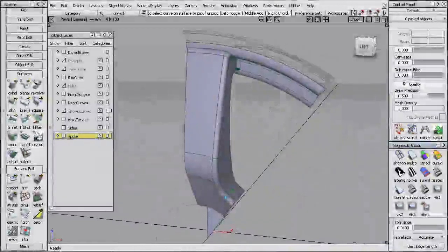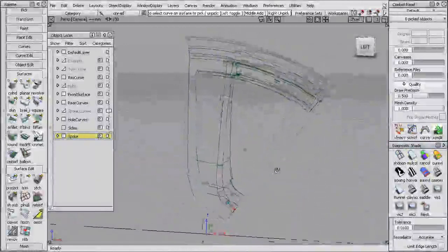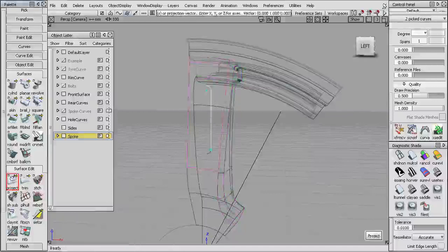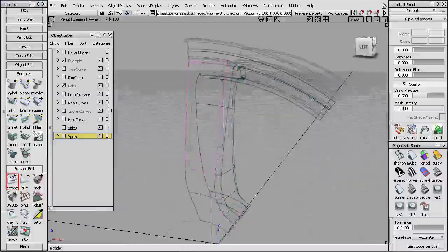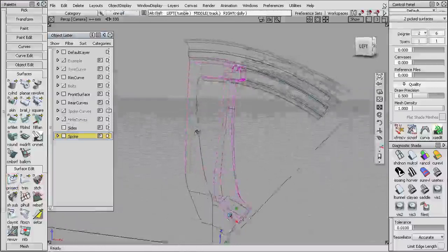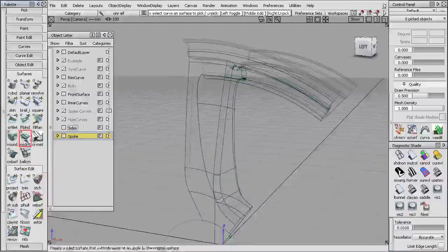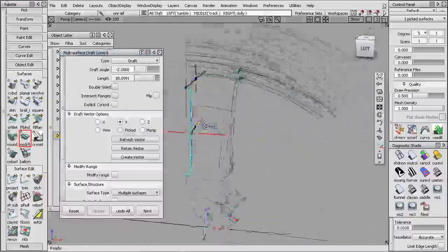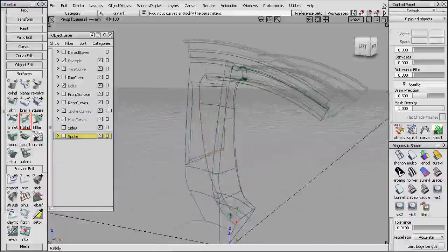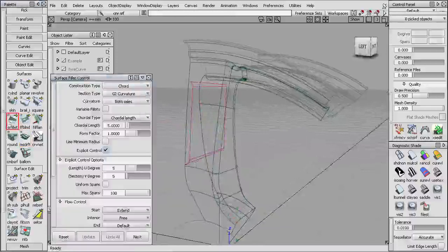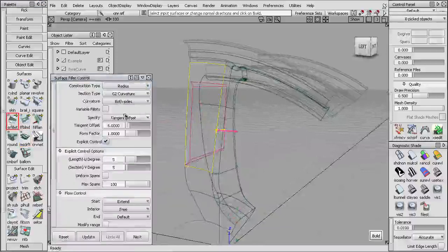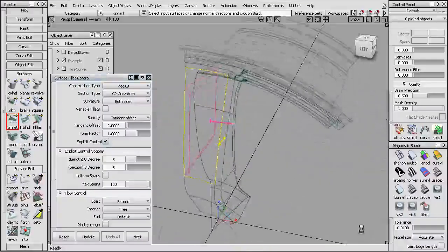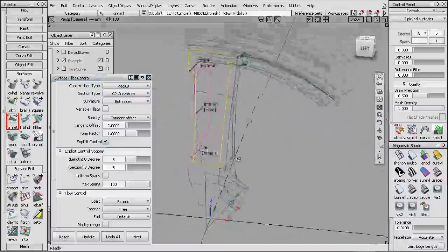And then to finish off, I've got some curves to put a hole detail into the spoke. And one of the really nice things about Surface Fillet is that we don't need to intersect and trim first. So I can just project the curves onto the front surface and then build the draft surface directly from them. I don't need to trim the front surface first, because the fillet will do that later. So if I now fillet these three surfaces against that front surface, and I'll just do a normal radius fillet and a fairly small one for now. And I can build that, and it does the trimming and creating the fillet surfaces at the same time.